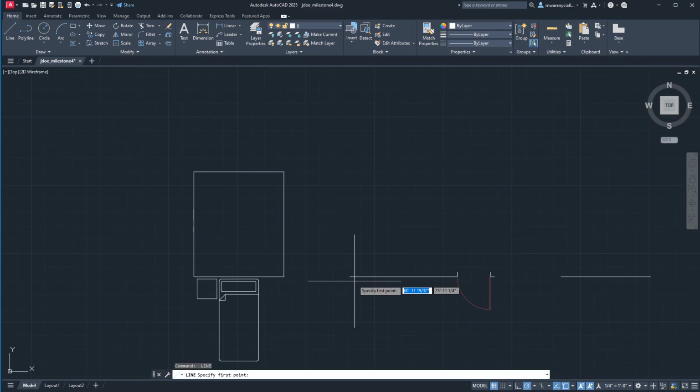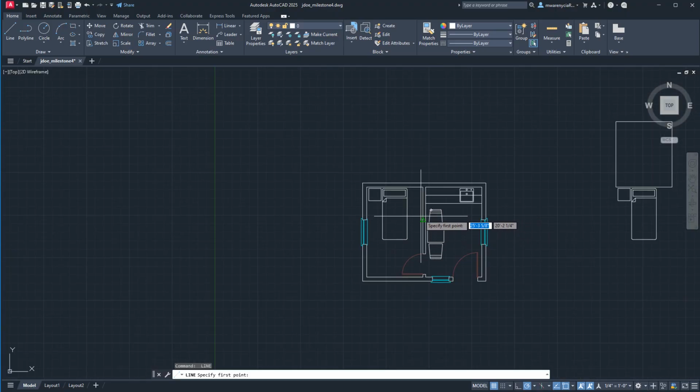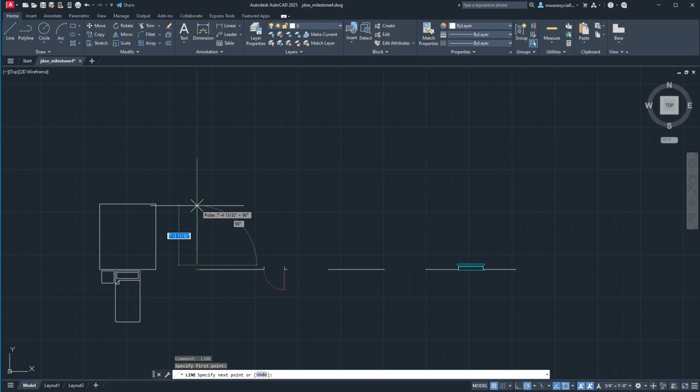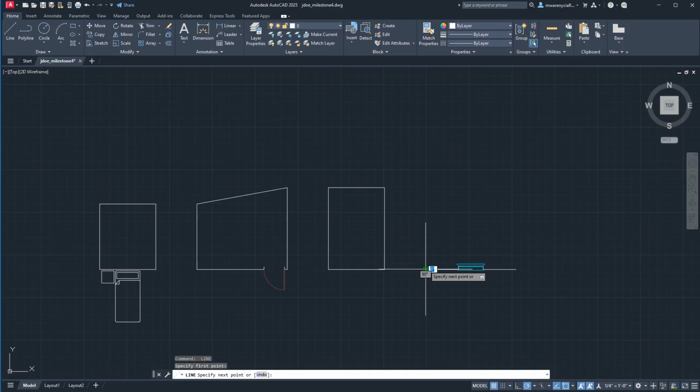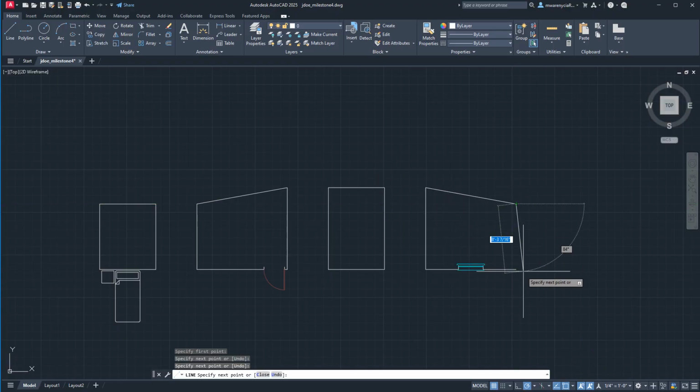So there's our 8 foot wall. Now this is going to be our east wall right here, and this is going to transition from 8 foot on the left side to 10 foot on the bottom side here. So what I'll do is draw another 8 foot. Oops, that's 8 inch. And then over here, I'm going to do 10 foot, and then we can draw that down. This wall is going to be 10 foot on both sides, so I can just turn this into a square. And then this one again is going to start out at 10 foot and come down to 8 foot.